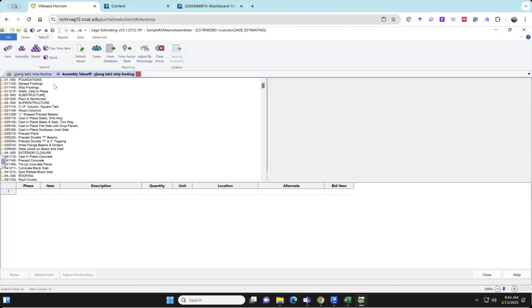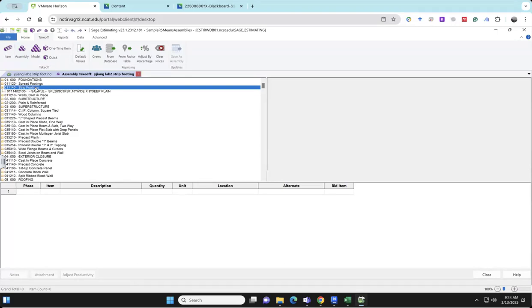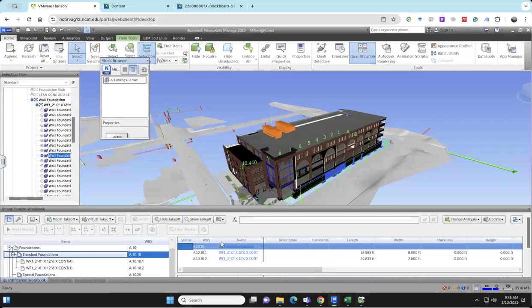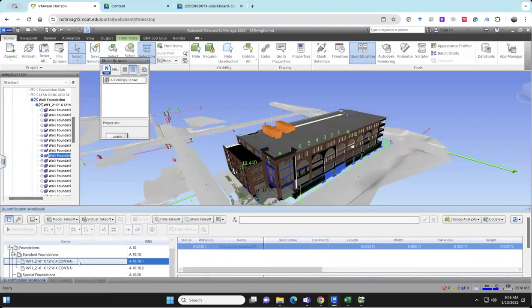So today we did a strip footing. And here has a sample strip footing, which is 0, 11, 14, 0. And you click this strip footing, and you will see this has a sample over here. And this sample is using a name which is different to ours, and also the size is different to ours, because it has 16 wide and 8 deep. What is the size and the information for ours? Ours is 2 feet wide and 12-inch deep, right?